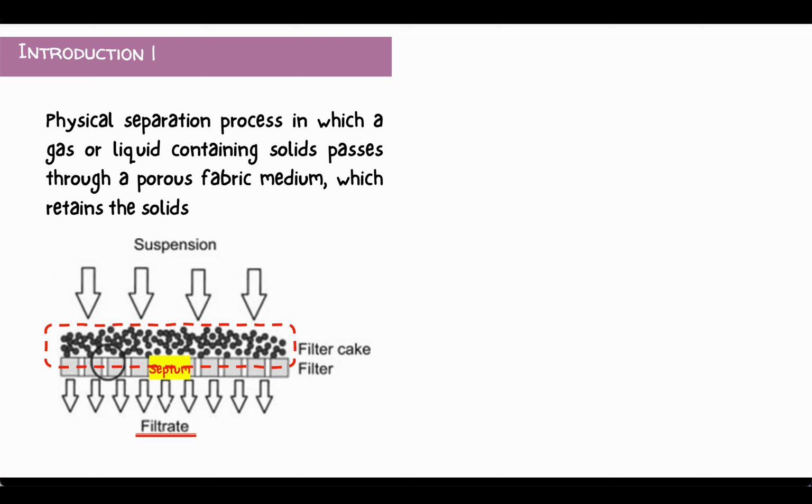As in other separation processes, the separation of phases is never complete. Liquid adheres to the separated solids, which is caked with residual moisture, and the filtrate often contains some solids, which is the solids content in the filtrate or turbidity.